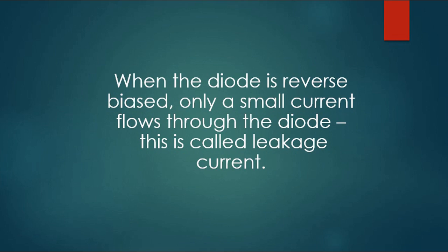When the diode is in reverse bias, a small leakage current will be flowing through that diode, and it can only be visible if you use maybe an analog multimeter, because the meter that I often use is a digital multimeter, but I have some colleagues, friends that we work together in terms of electronics, and I have also seen it